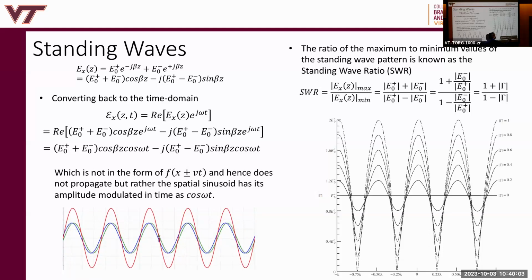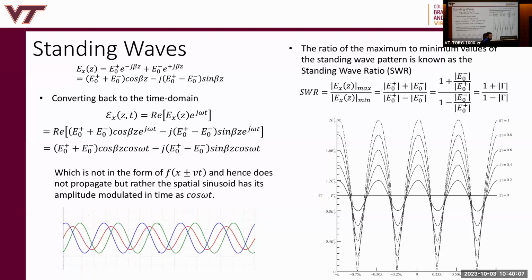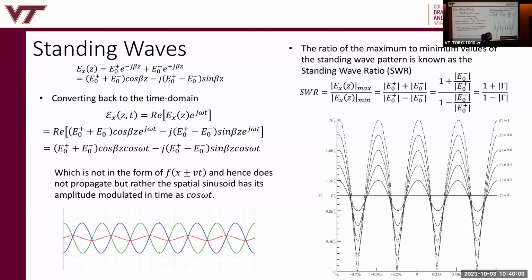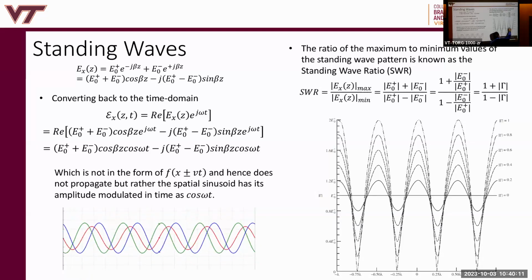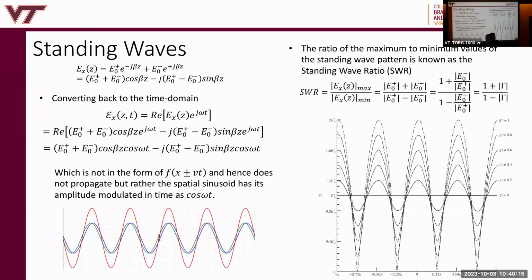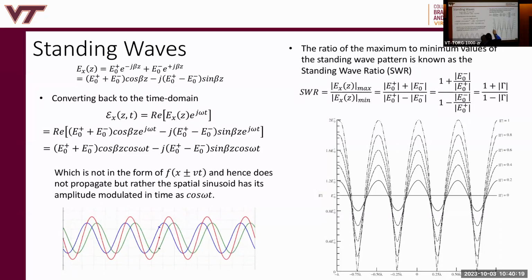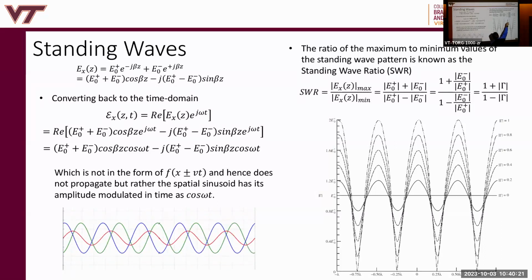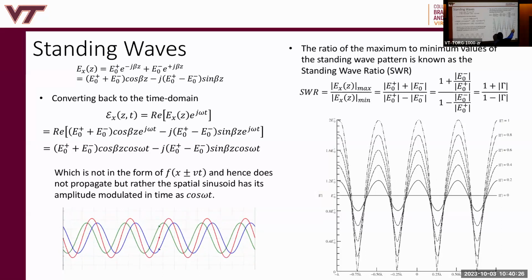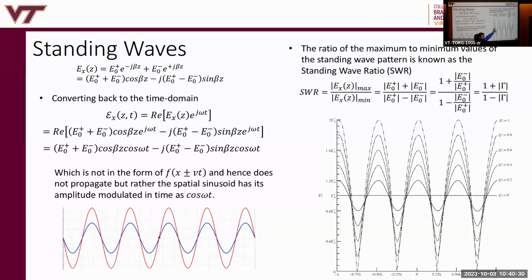All right. If the reflective surface reflects only 20% of the light that's incident upon it, then we get this standing wave ratio, plotted as a function of the z coordinate here. The magnitude of gamma is 0.2, so E naught minus, which is 0.2 times E naught plus, gives us the superposition with a maximum of 1.2 E naught.